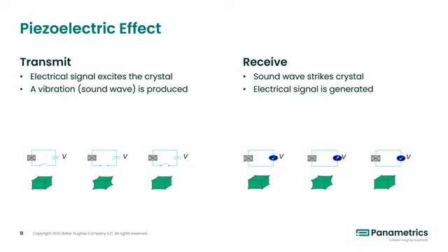When the transducer is transmitting, the circuit will close and be completed, causing current to go to the transducer crystal, exciting it, causing it to vibrate and generate these sound waves. On the receiving end, the receiving transducer is listening, so that circuit is closed and completely listening until that sound wave strikes the crystal, causing it to vibrate, and then that vibration is turned into electrical energy to be returned to the meter electronics.